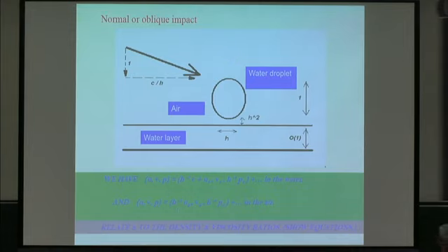And then in the air, well, the pressure continuity demands an h to the minus 1 on the pressure. The kinematic condition demands v be order 1 again. And then continuity in this thin gap tells us that the horizontal velocity must be large by a factor h to the minus 1. So from that then, we're getting a fairly complete picture of the water and air combination in 2 dimensions. It works also in 3 dimensions. Then we want to relate that small parameter h to the density and viscosity ratios, which are small.